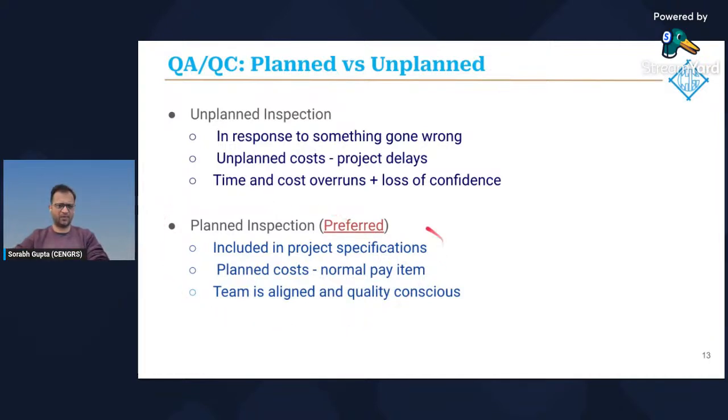And I think the best way to do it is define in writing a strong QA/QC plan for your deep foundations. Decide what kind of tests we need to do. Carry out a very robust initial pile test program, use that as a benchmarking tool, and then define what we will do for the routine or the production piles.